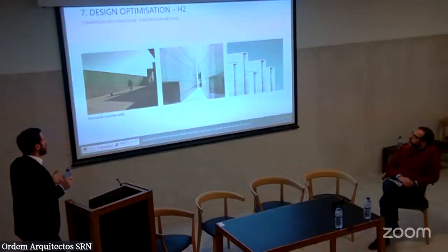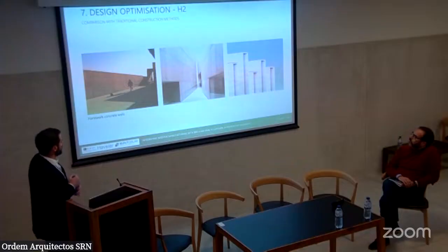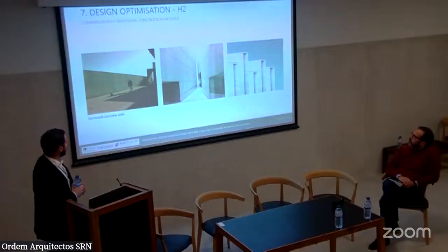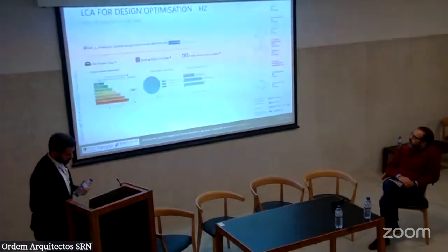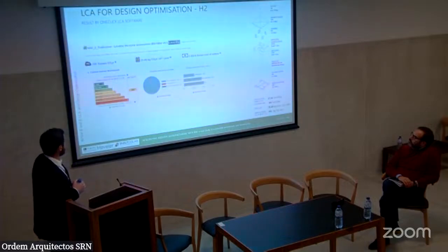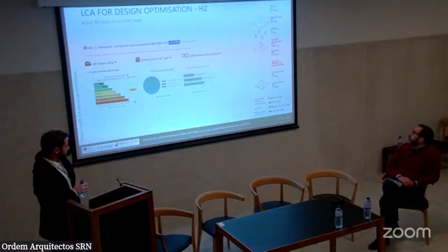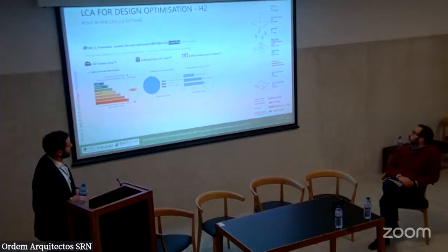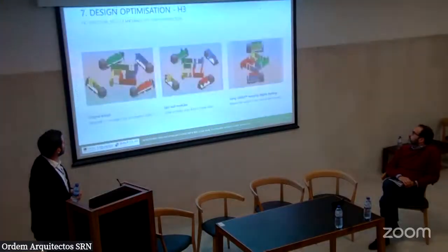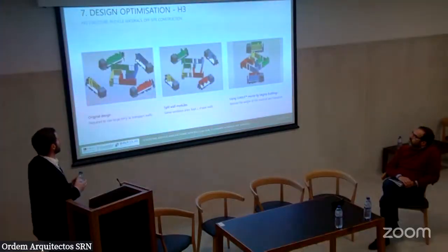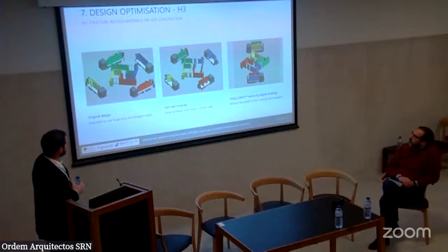After this, and making the context to the global construction, we decided to do a comparison with the same house, using formwork for concrete walls for the same shape, which we automatically assumed is even worse, and which goes to the D category. The reinforced concrete walls will go up by 52%, which is 27 tons of CO2 emitted, which of course proves what everyone thought.